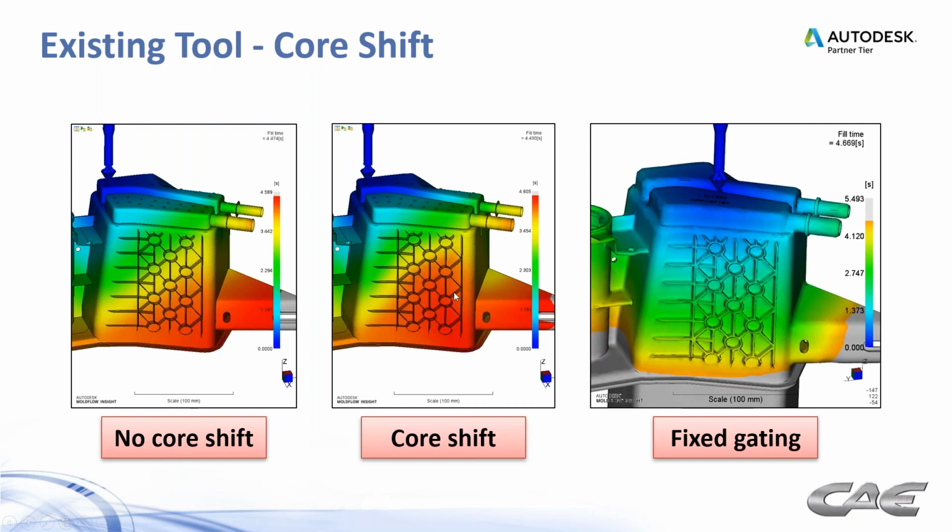Well, when we went back and actually measured some parts in this case, because we knew we were going to start playing around with wall thicknesses, we built a mid-plane model to be able to do so. So we modified the wall thicknesses on this to mimic what they were seeing in reality. And sure enough, we're seeing this backfilling condition here.